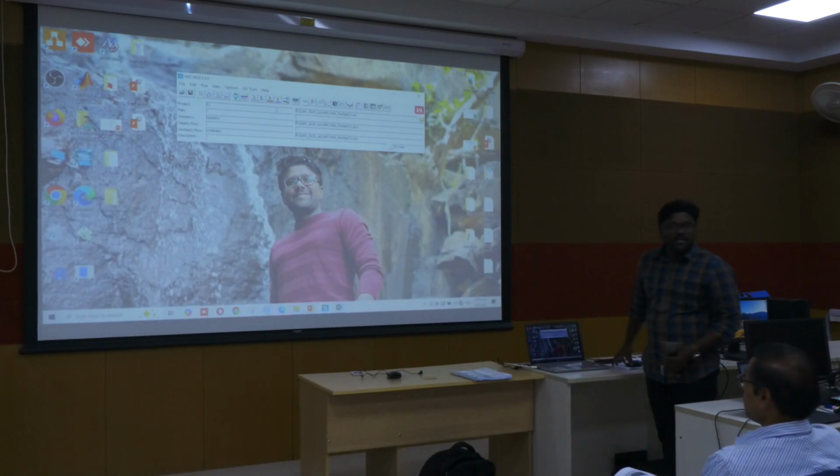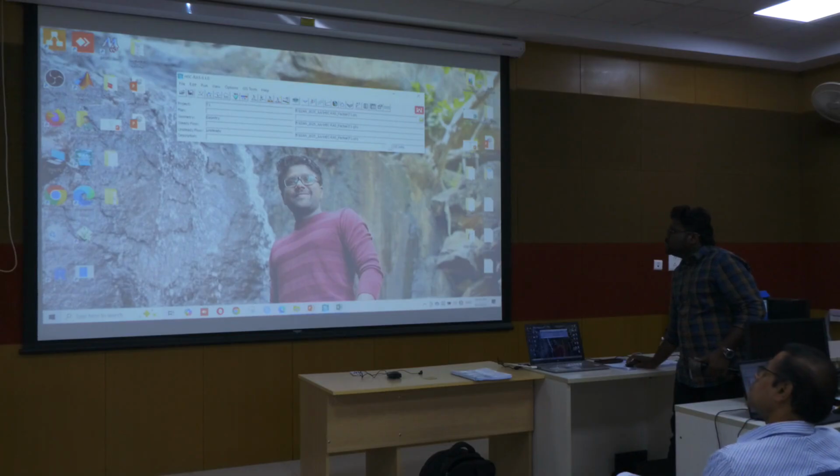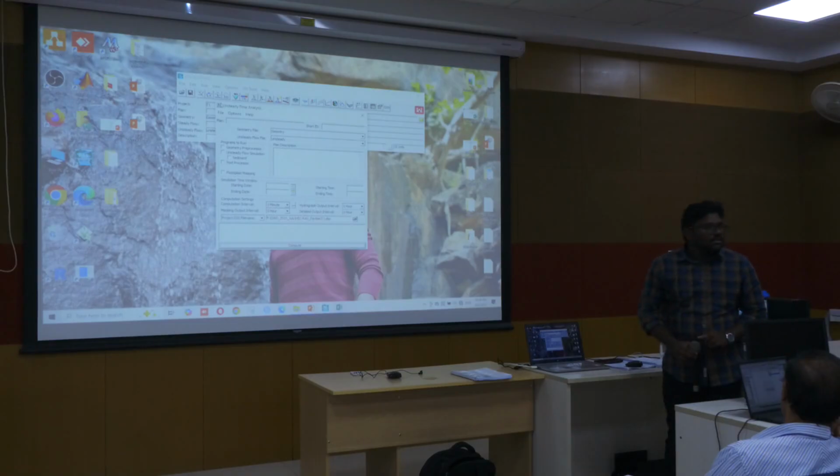So after that, we need to run the unsteady flow. To run that, just save it once. Click on run, click on unsteady flow analysis. It is like our control panel.